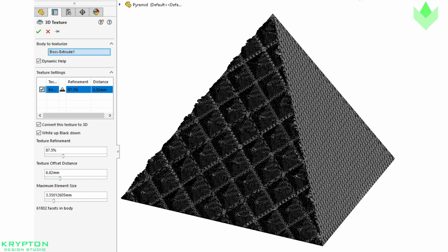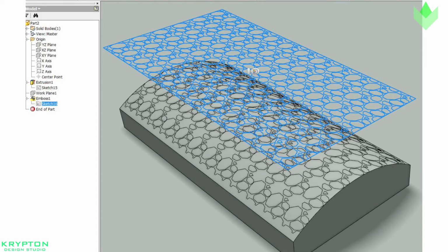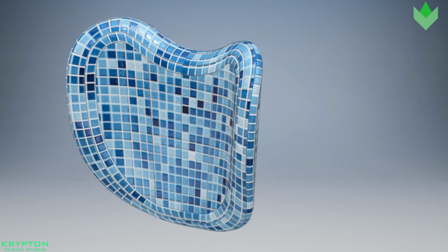When applying a texture to the part, the CAD drawing must be adjusted to accommodate this surface variance. If the texture is on a surface that is perpendicular or angled away from the mold opening, then no draft changes are necessary. If the texture is on a surface parallel with the mold opening, however, increased draft is necessary to prevent scraping and drag marks that could occur during part ejection.